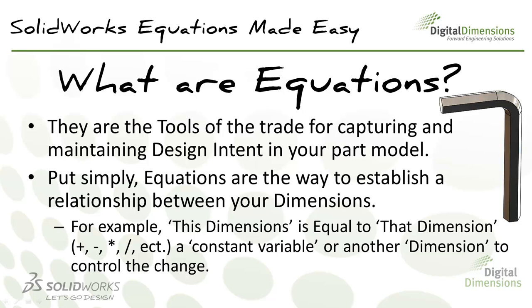And now the main question, what exactly are equations? Well, here I describe them as the tools of the trade for capturing and maintaining our design intent in our part models. Well, put simply, equations are the way in which we can capture and maintain relationships between our dimensions. For example, this dimension will be equal to that dimension plus 5, or this dimension is equal to that dimension plus another dimension. So we have the ability to set a relationship between our dimensions with equations.